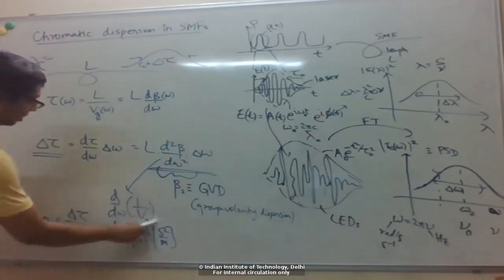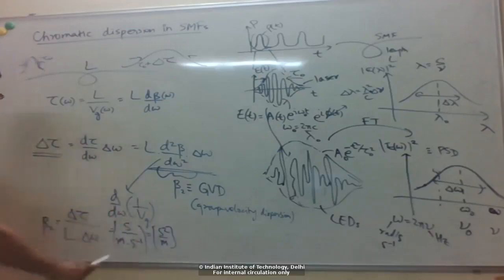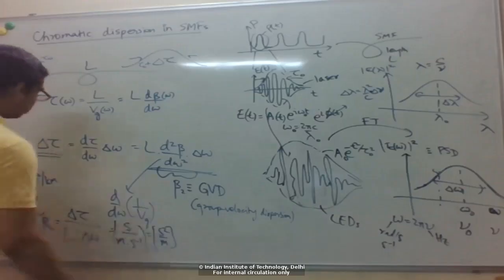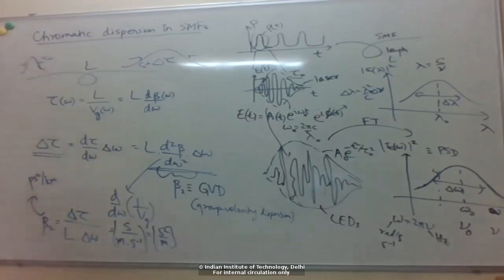You can also check from here. Right. So typically, for fibers, this is denoted in picosecond square per kilometer, because in those units, they come out to be some actual numbers instead of carrying some 10 to the minus 23. So they're denoted in picosecond square per kilometer.